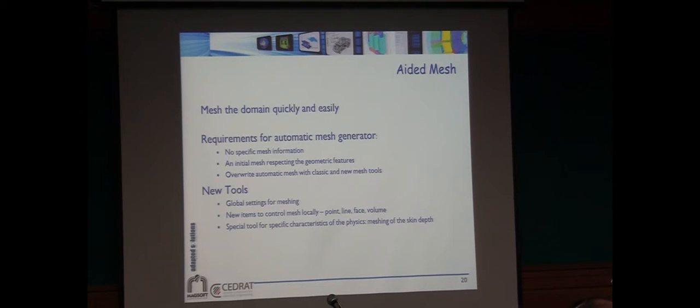By the way, if you bring a file from a previous version and you are trying to use this new mesh generation, it will automatically overwrite all the information that it had from before. You can do global settings, and as I say, you can control locally, and you can also, and this is done by macros, make a mesh which is specifically associated to such things as skin depth.